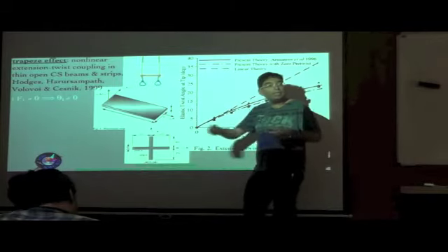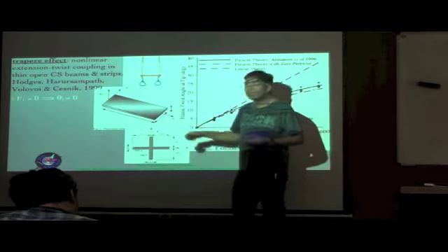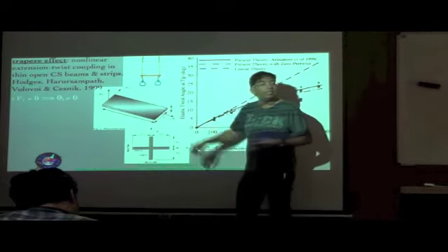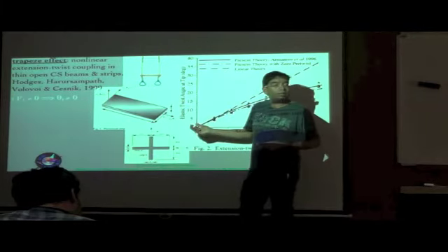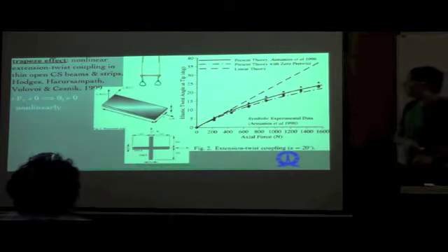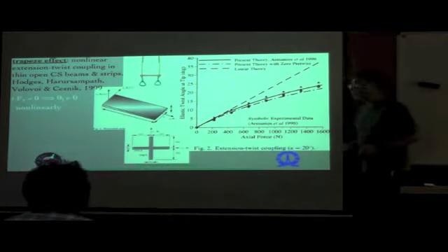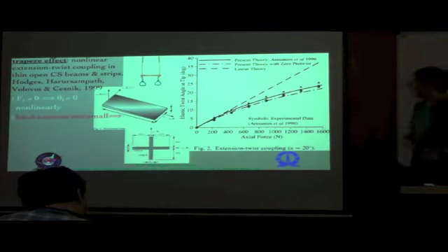So F1 is nothing but an axial force, and theta 1 is a rotation about the x1 direction, which means that it is a twist. So a non-zero F1 results in a non-zero theta 1. That is the extension-twist coupling. And of course the fact that it is nonlinear is very clear from this particular example plot.